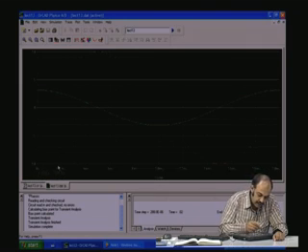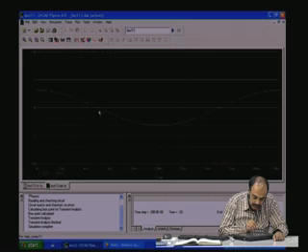The red one is the voltage that you are applying, you see that it is starting from 0, and the current, which is the current through the capacitance, is already at the positive peak, and then it goes down, cuts 0 at 90 degrees corresponding to the voltage, and then reaches the negative peak when the voltage is 0, and so on.